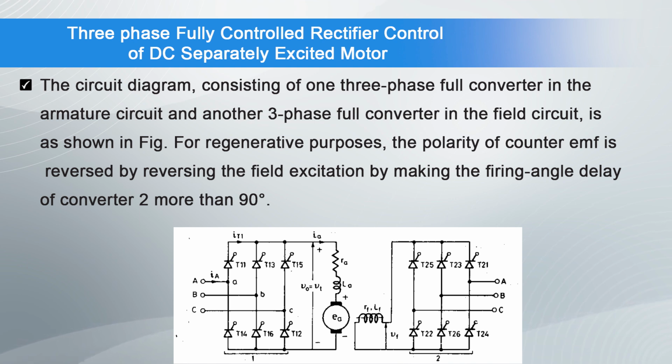For regenerative purposes, the polarity of counter EMF is reversed by reversing the field excitation, by making the firing angle delay of converter 2 more than 90 degree.